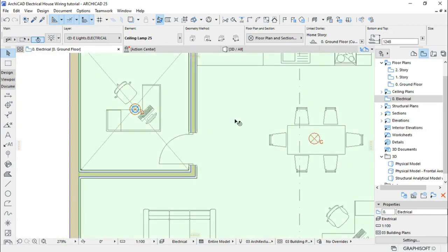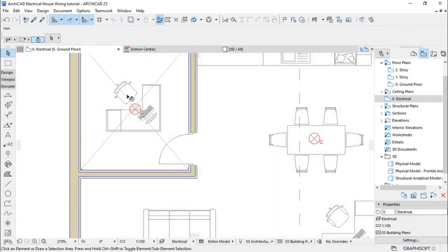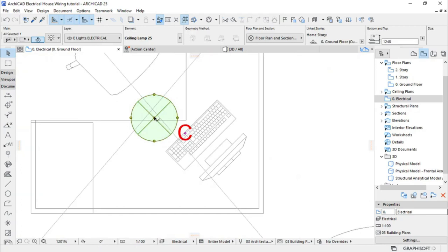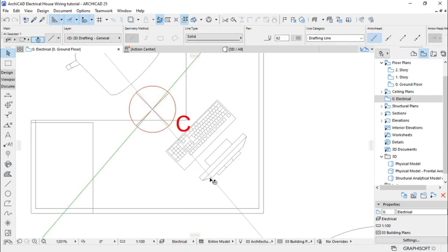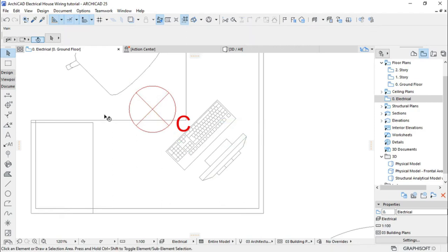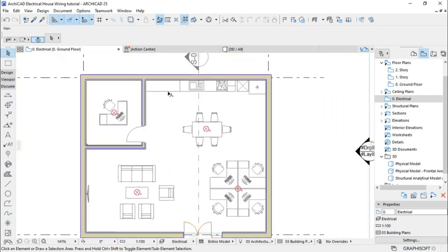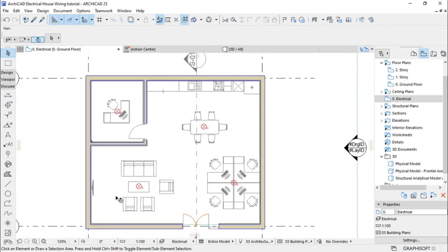So what we're going to do, escape and make sure you ungroup there. Then now you can move this object alone, just like that. And then you can get rid of these two lines. There we go. If you zoom out, that's exactly what you wanted.